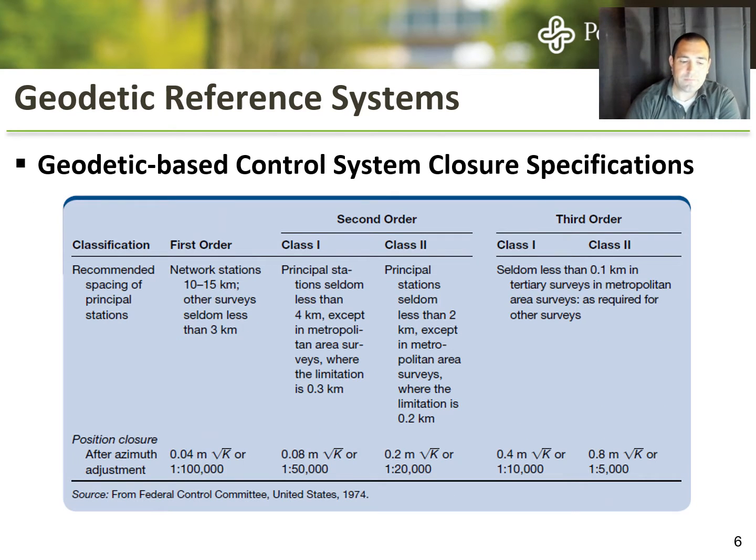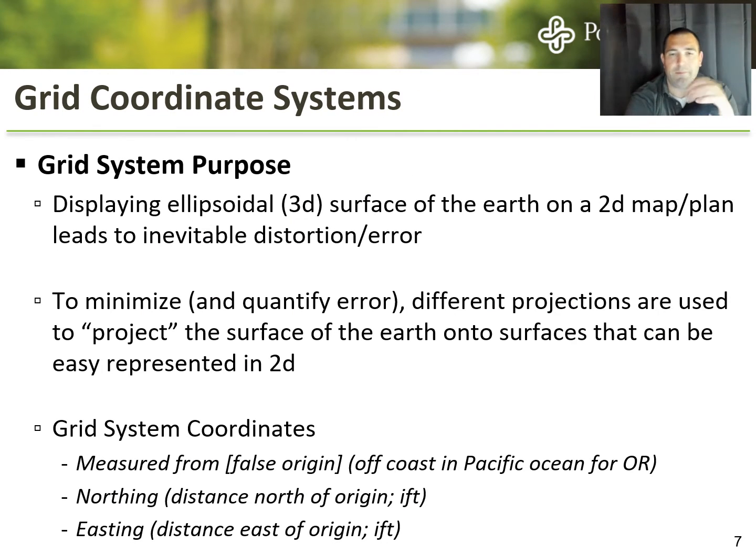However, as I mentioned before, and this is just more of what we were just talking about a second ago, almost all of your work in engineering, whether it's on the surveying side or more likely on the design side, is going to be based off not geodetic coordinate systems, but grid coordinate systems. So grid coordinate systems are a useful approximation of the curved surface of the Earth.